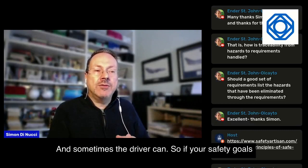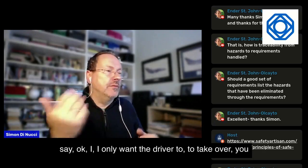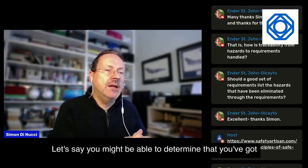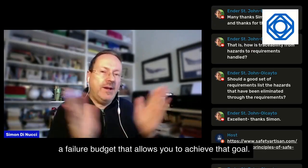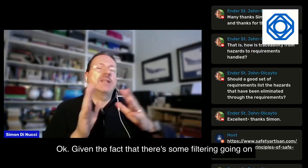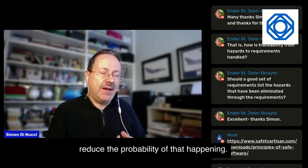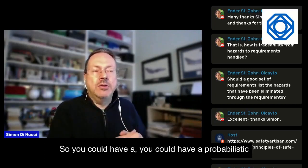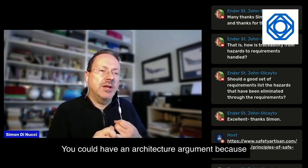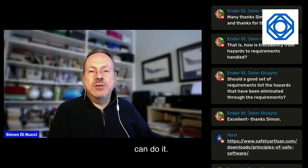So if your safety goals say, I only want the driver to take over no more than once in, I don't know, 100 driving hours, you might be able to determine that you've got a failure budget that allows you to achieve that goal, given that there's some filtering going on with external controls that reduce the probability of that happening. So you could have a probabilistic argument for still meeting your safety goals. You could have an architecture argument because you've got backups, etc. There's different ways you can do it.